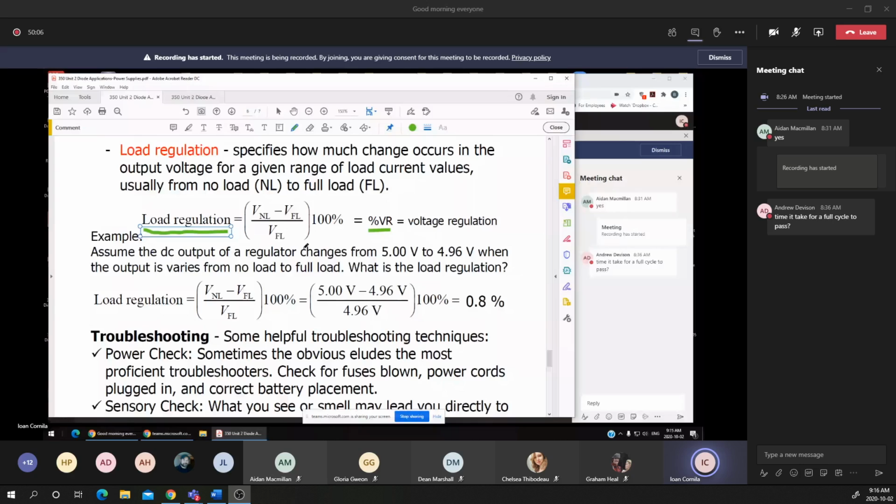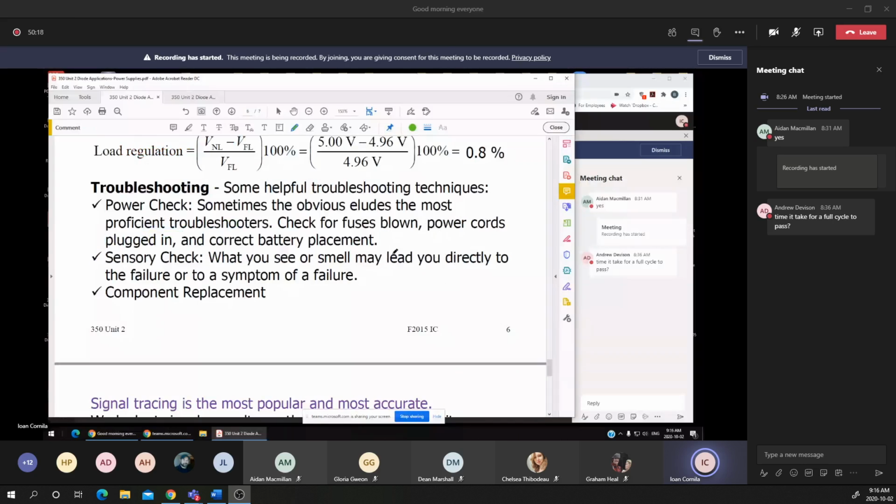Now, in terms of troubleshooting, I'm just giving some ideas. We have to check the parts, the components. Now we know what we expect, and we have to visualize the waveforms. Having a voltmeter or a multimeter is not always enough to troubleshoot a power source. First, check the supply voltage. Do we have the input voltage?